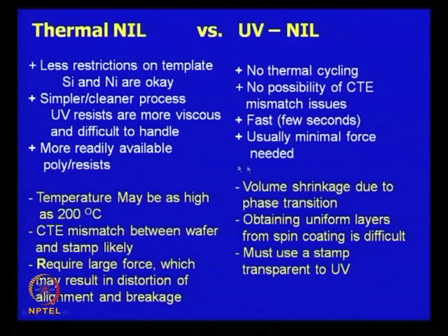Advantage of UV NIL, of course, there is no thermal cycling. So, you save on the hardware, you save on the critical issues of heating, controlling the temperature, then cooling it down and then detaching. So, it is far less step intensive, I would say. Any possibility of thermal coefficient mismatch issue does not remain at all. So, there is no possibility of coefficient of thermal expansion mismatch.